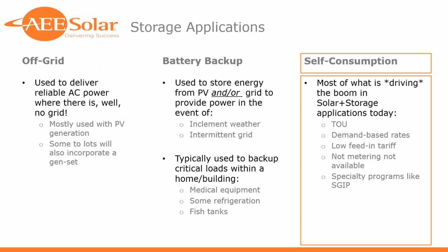This is the point where I'd have to talk a little bit about application stacking. In few markets in the United States would you see that the applications on the right under self-consumption would be enough to really justify a solar plus storage system. In almost every market we're in, we're having to combine one or more of these aspects of self-consumption with backup. I think when you get down to it, the economics are such that adding storage doesn't pencil out just based on energy arbitrage for time of use or getting a rebate from SGIP. You've really got to combine that with a practical advantage like backup that you can sell a homeowner.